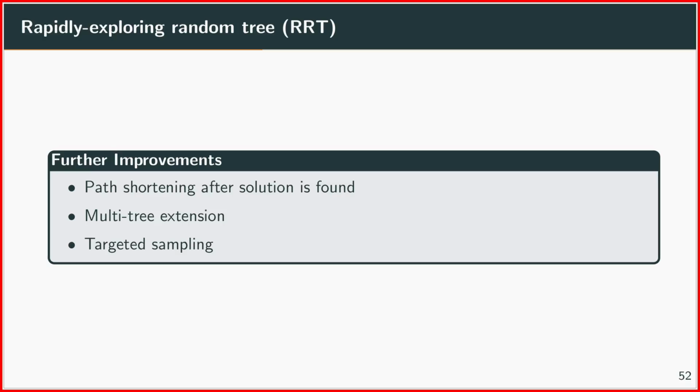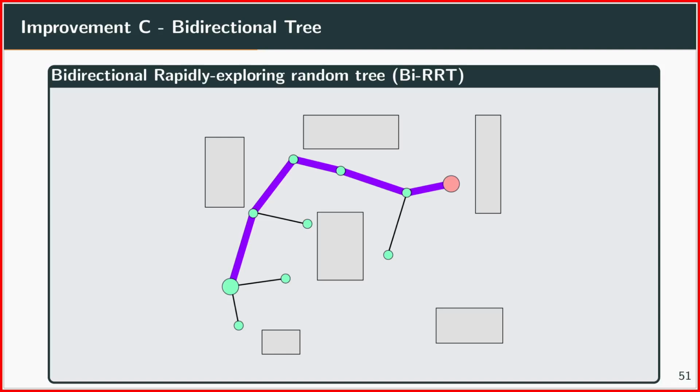What's the best way to do the path shortening part? Mm-hmm. I think we touched on it last time, but yes, the basic version is that you randomly sample 2 points on your path, and then you try to connect them, and if they are connectable, then you add them as an edge and you delete everything in between.